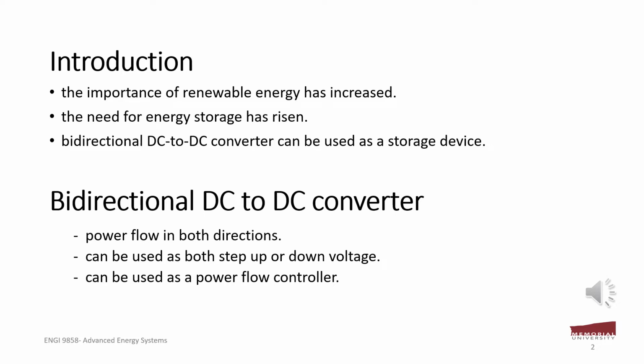Moreover, in electric vehicles, bidirectional DC to DC converters are used for capturing the kinetic energy of the motor and charging the battery during regenerative braking by reverse flow of energy. Similarly, the output of a hybrid system consisting of wind energy, solar energy, and other renewable sources is environment dependent, so fluctuation of output power and sudden changes in load demand make these hybrid systems unreliable. The solution for this issue is to use a storage system like a battery or supercapacitor with the help of a bidirectional DC to DC converter for power conditioning and smooth flow of power to the load.